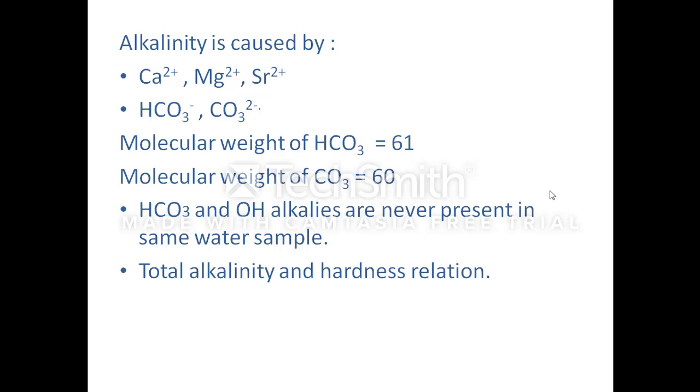Now the next case is when alkalinity is greater than hardness. Then all the hardness will be caused by carbonates and bicarbonates. That's only carbonate hardness will be present and non-carbonate hardness will be equal to 0. And the total hardness will be equal to carbonate hardness.